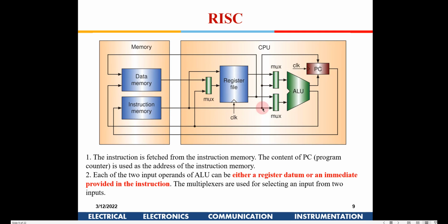In those cases the result of this is also going to go back to the register. It cannot go back to the data memory. The only time the ALU will provide data to the data memory here is when sometimes we need to calculate the data memory address, right?